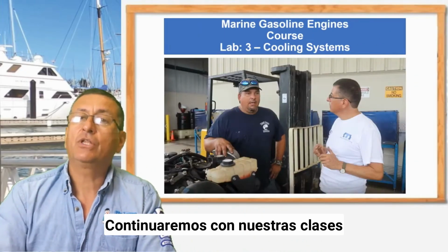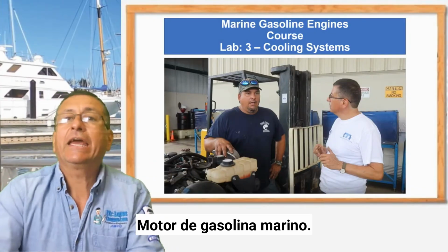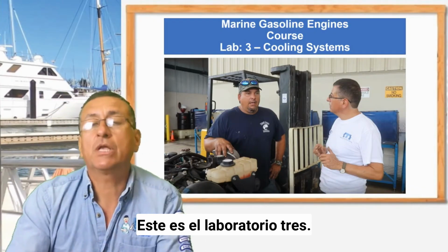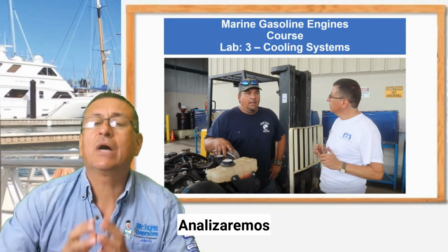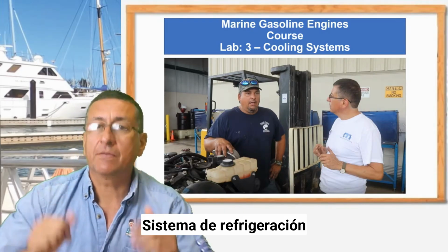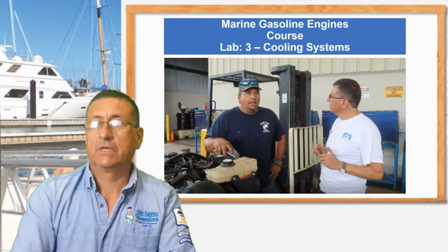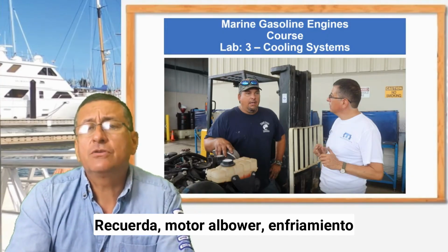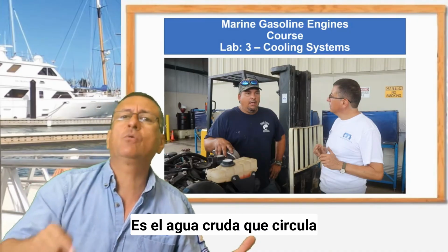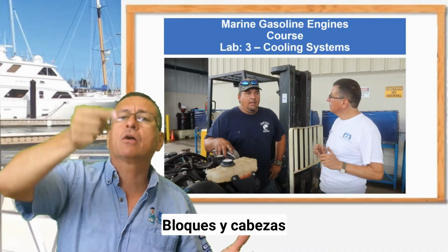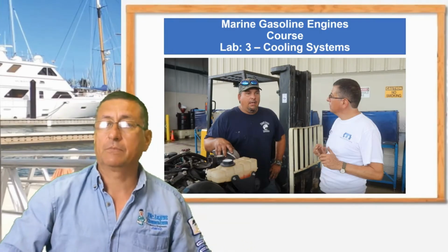Today we are going to continue in our class of marine gasoline engines. This is laboratory number 3. In this laboratory we are going to analyze the cooling system for inboard engines and outboards. Remember, for outboard engines, the cooling system is a raw water system. It's raw water circulating to the block and the head and returning outside through the middle of the propeller.